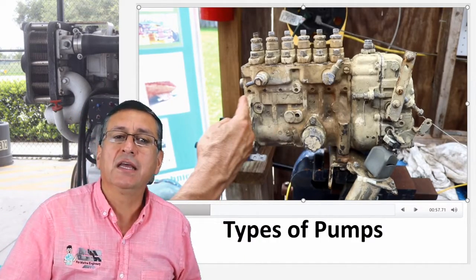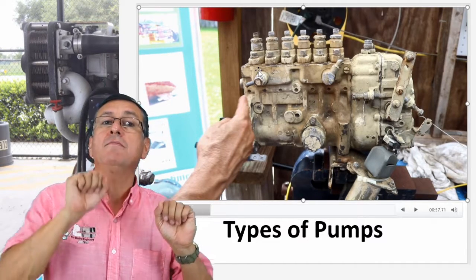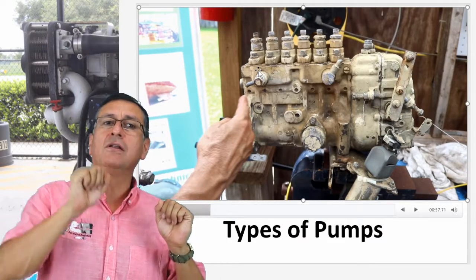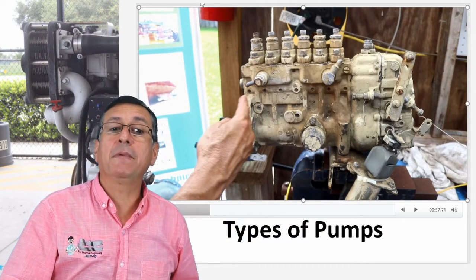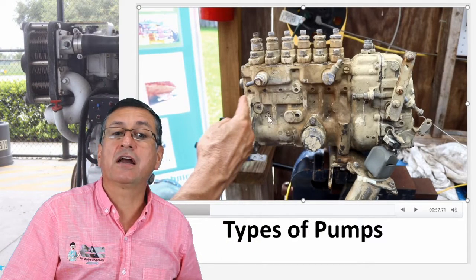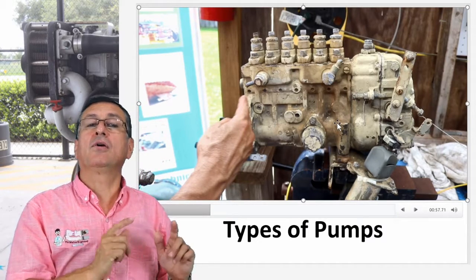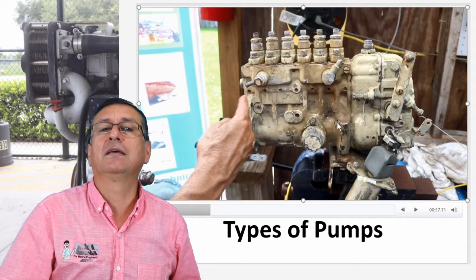What is the meaning of that? Plunger number 1 works at the same speed, the same angle, as piston number 1 of the big engine. Because the position of the lobes in the camshaft, the angles of the lobes, are exactly the same as the angles of the lobes in the big camshaft. Right now we are going to check that situation.